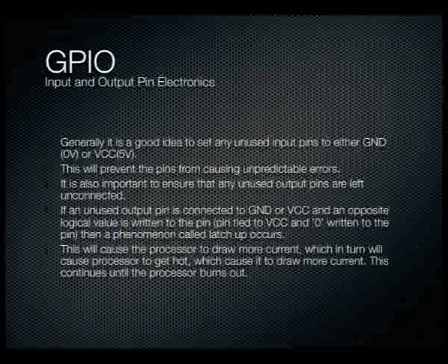Okay, if you're really paranoid, make any unused output pins inputs, and then if you do connect them, it's not really going to be a major problem. So we want to ensure that we don't have the phenomenon known as latch up occurring, which causes the processor to draw excessive current and simply burn out.